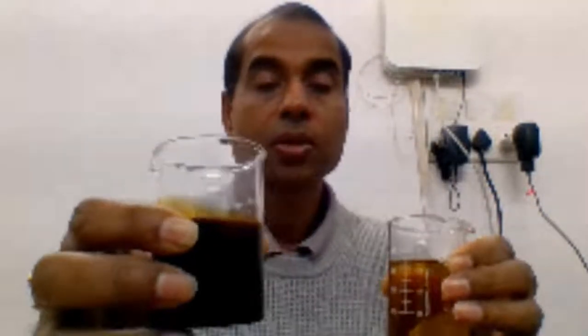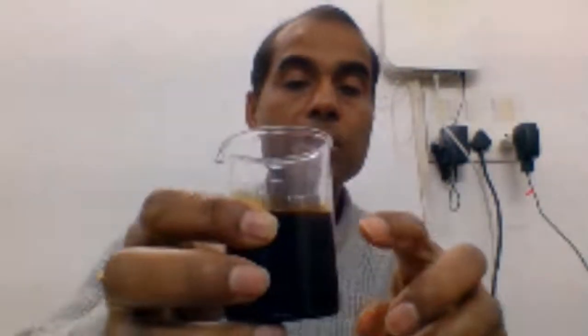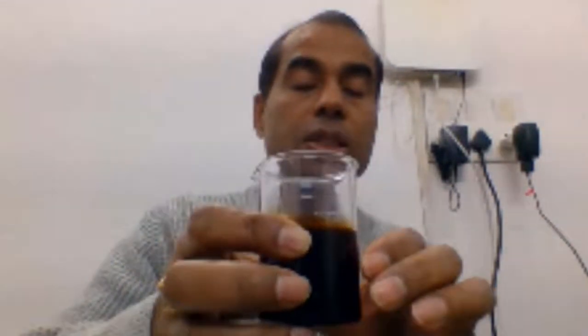Because of the detergent and dispersant, the particles are all dispersed inside. They don't settle down, and therefore they do not form any kind of deposit in the engine. So they keep the engine still good, but what is important is we should change the oil. So this is very, very important, the lubrication part. But it is not only lubrication. Tribology, as you are learning from the very basic things, includes many things: materials, lubrication, calculation of forces, velocities, temperature, understanding of the temperature, understanding the environment. All put together makes a good tribological system.